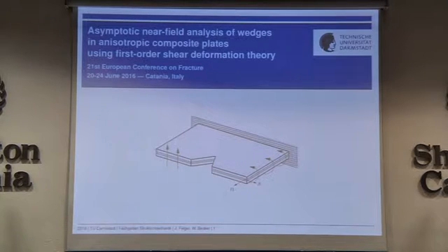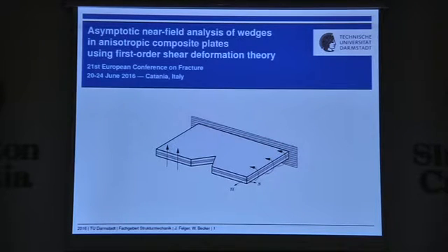So, as depicted here, we consider notched anisotropic composite plates, and we are interested in the asymptotic near-tip field here within the framework of the first order shear deformation plate theory.